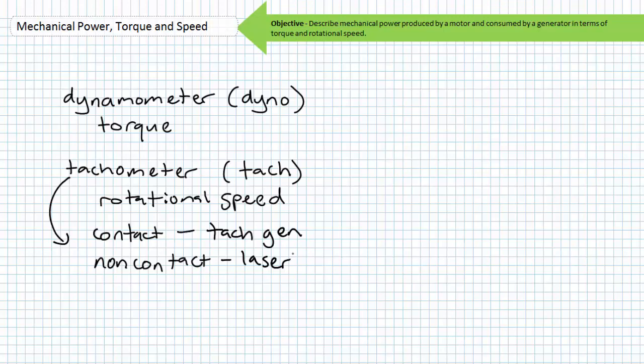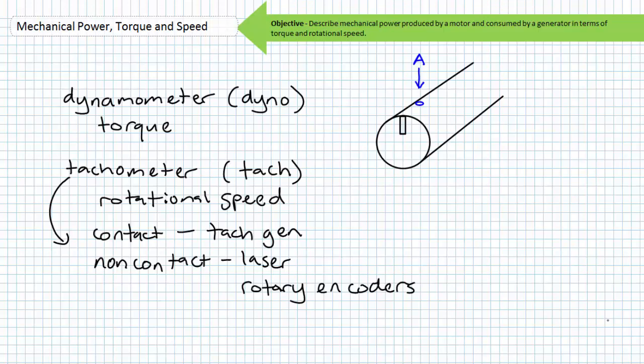You don't need to pay some unschooled youth $8 an hour to sit there with a laser tach to get valid rotational speed readings, because there are numerous automated methods of doing so, all falling under the blanket term Rotary Encoders. If all we're concerned about is rotational speed and not direction or position, a single Hall effect sensor on a shaft is more than sufficient to do so.